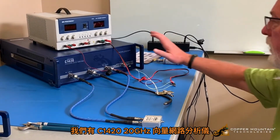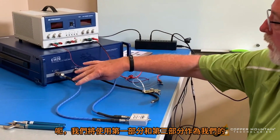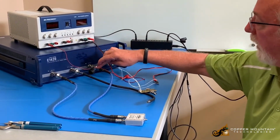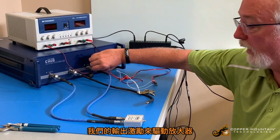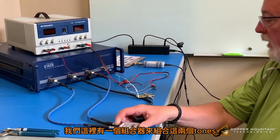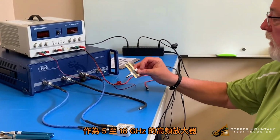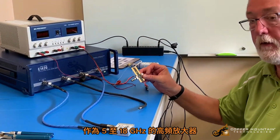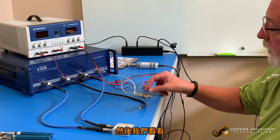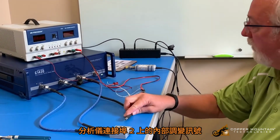We have our C1420 vector network analyzer. We're going to use port 1 and port 3 as our output stimulus to drive the amplifier. We have a combiner here to combine those two tones. We'll run those two tones through this amplifier, this high frequency amplifier from 5 to 18 gigahertz. And then we'll look at the intermodulation products on port 2 of the analyzer.